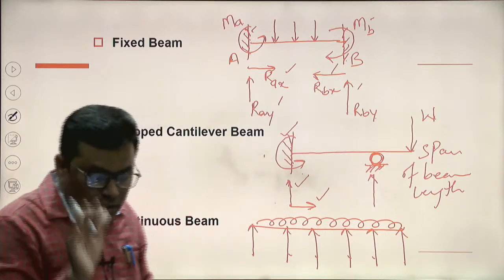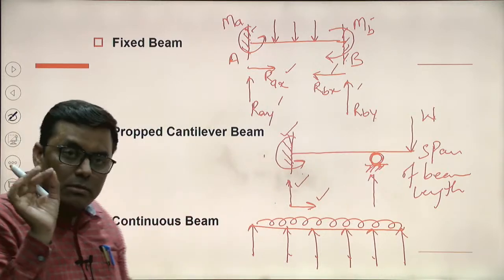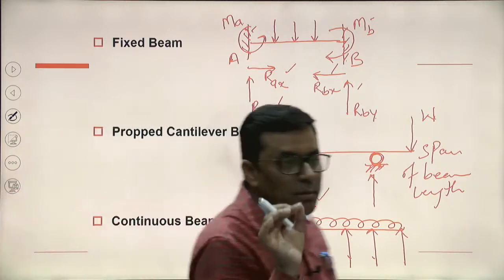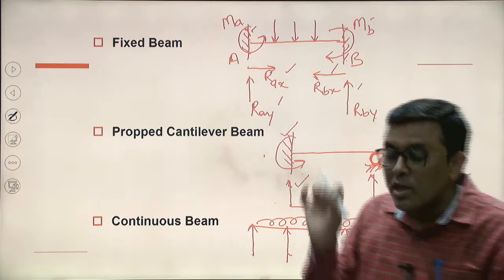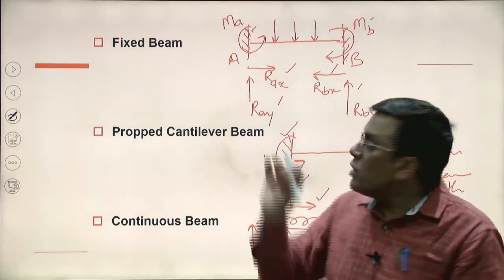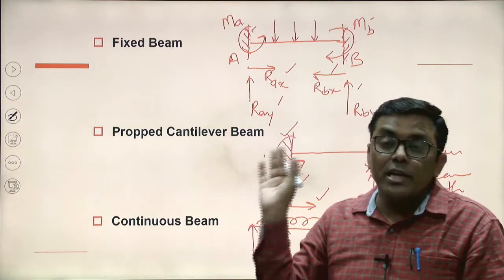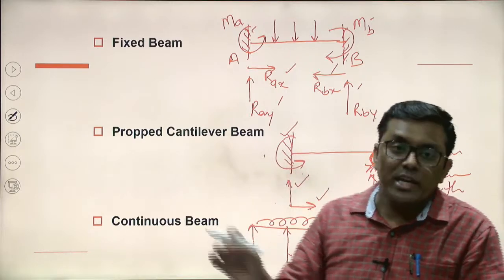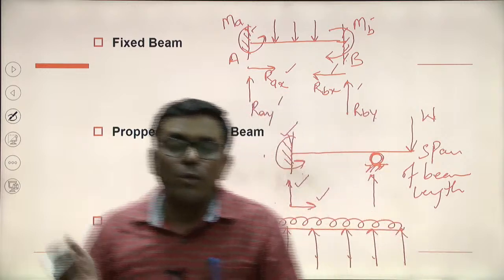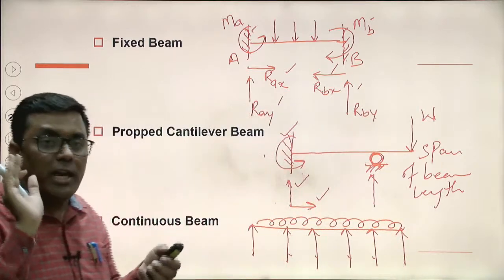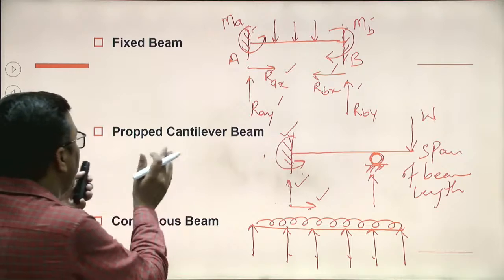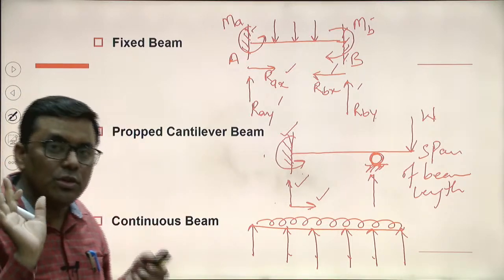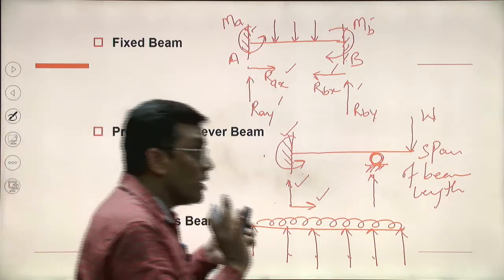तो मेरी तरफ से जो क्वेश्चन फ्रेम होते हैं, फर्स्ट बीम क्या है, then differentiate between statically determinate and statically indeterminate beam, then draw the free body diagram for statically determinate and indeterminate beam. It depends on marks. If it is a 2-mark question, then 1 point definition is okay. If it is a 5-mark question, then we have to draw the free body diagrams and we have to justify with the number of unknown reaction force. So this particular question comes very often.